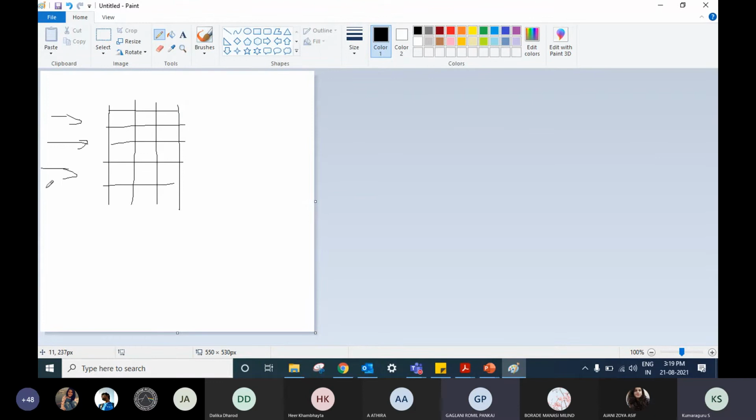When this is undergoing a lateral force, because of the fixed connections between the beam and the columns, it has some resistance to lateral sway. Now, the first thing is a beam-column system should be rigidly connected, right? We saw this, like a simple frame. The first thing is to rigidly connect it, or you have a shear wall, or you have a bracing, which can take it. So these are the only ways we can make it laterally stable.